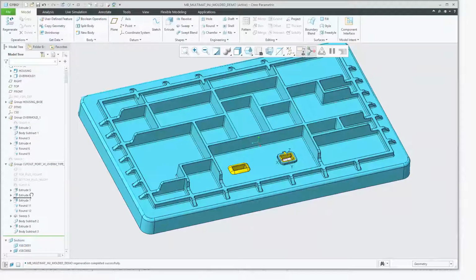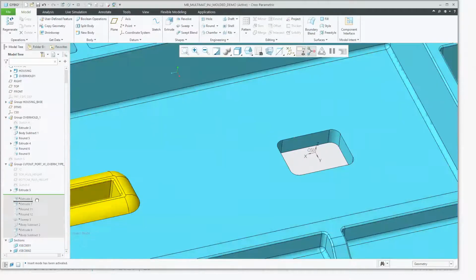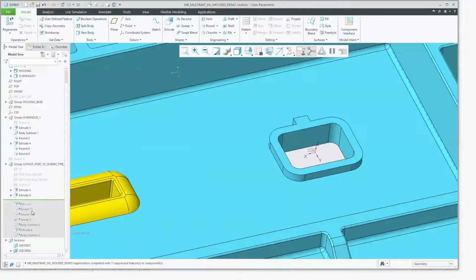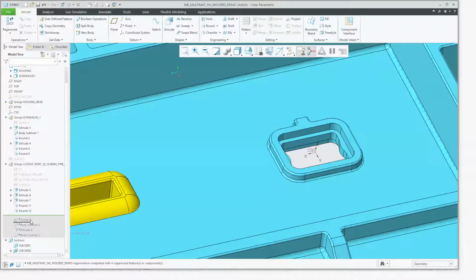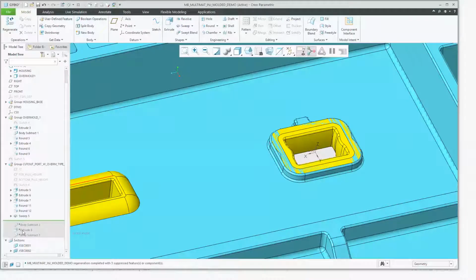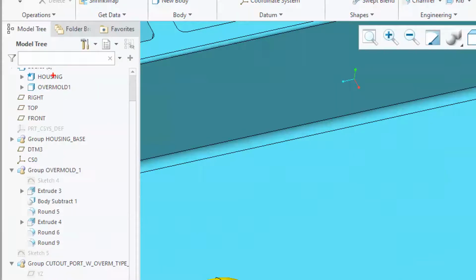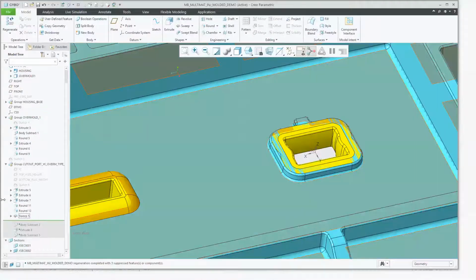And what it's really doing is there is a first extrude, right, based on the coordinate system, and then another extrude there, right? And this is where we are creating some rounds and everything, and this is where we're adding the next body, right? We can assign features to different bodies, right? It's contributing to this body or this body, right? I have a second body there.